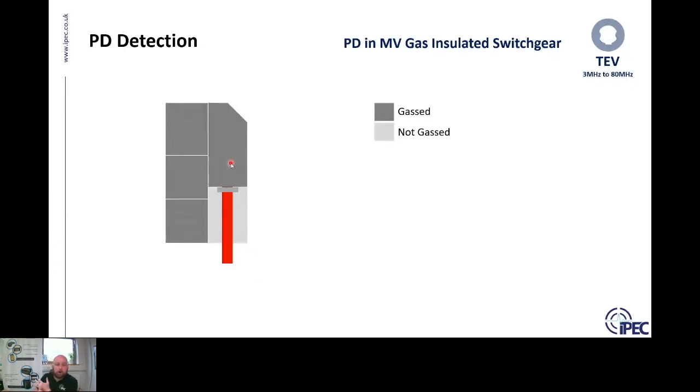Equally, it's not common practice for switchgear manufacturers to have UHF windows on medium voltage. It's not common practice for switchgear manufacturers to have pre-installed sensors on medium voltage switchgear. And if you run power networks, please lobby your switchgear manufacturers, because that would be a fantastic case.